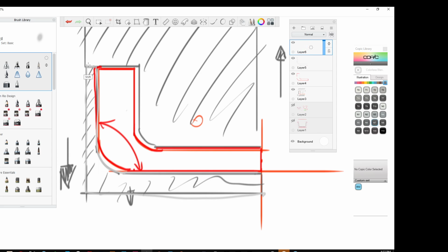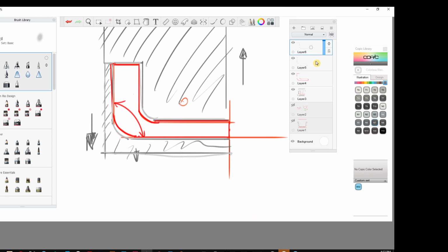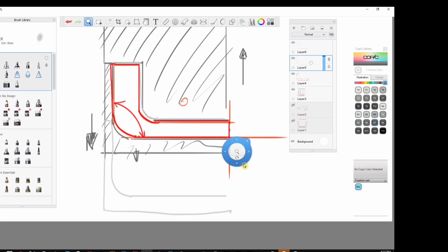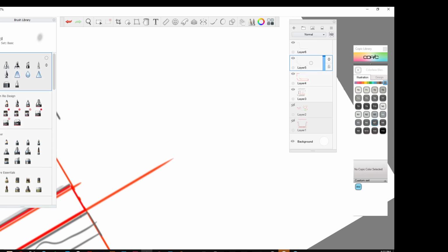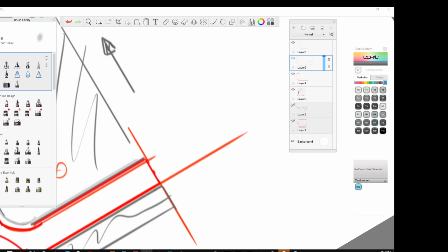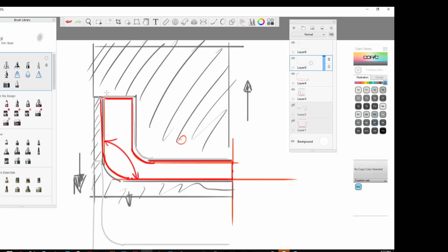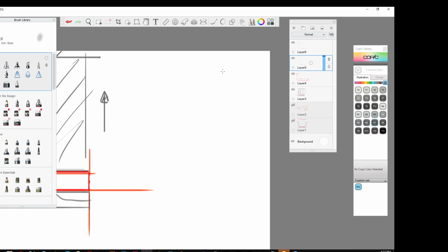Same as up here. We have to have that draft there. So what that does is it helps to ensure that as that part comes down, there's that draft there and helps make it smooth. So that's kind of how, when you look at your part, you know that that's what's going to happen. Now, if you have a part that has a parting line, so that was nice and perfect because it closes off here perfectly. If, let's say I have a part that looks like that.